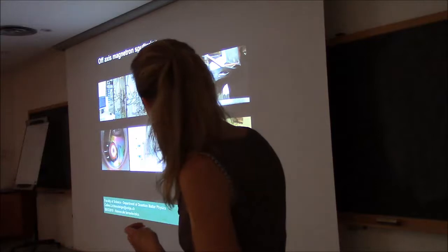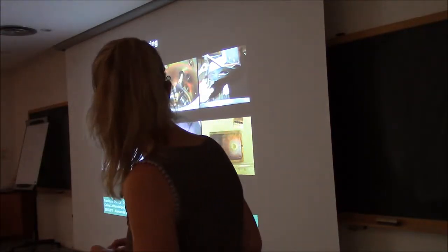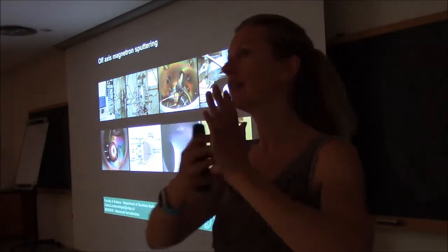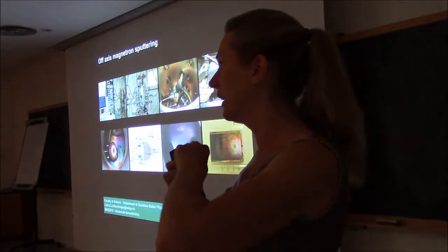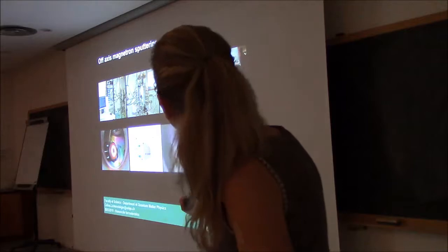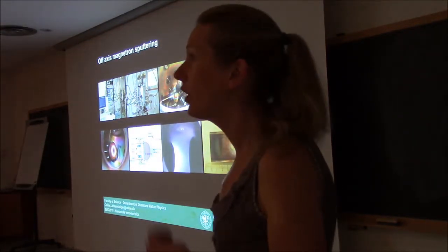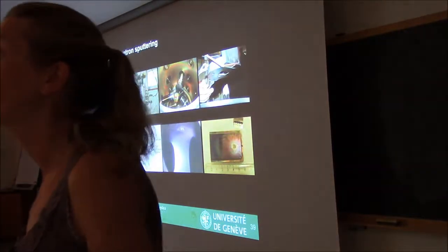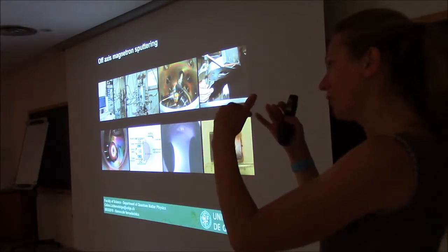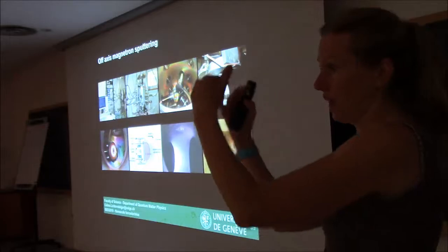And now the argon ions will be attracted to the target because of the magnet. So they will hit the target very strongly, which extracts atoms that fly everywhere in the chamber, and some of them will touch the surface of the substrate. If you have the right conditions in terms of pressure, temperature and so on, the atoms will stay on the surface, move around, and find the right position to epitaxially grow.